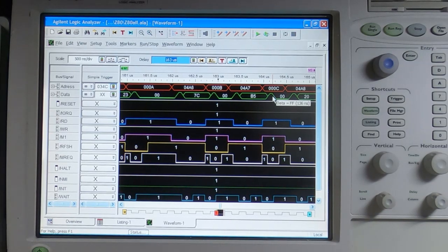So that's not surprising. The value we got from the DRAM when we were trying to do the memory check was 0000 as well. So it looks like that value is always returned from RAM, and that includes when the processor is trying to pop the return address off the stack, and in this case that's obviously going to cause it to reset. So it looks like the issue at the moment is that the value being returned by the RAM is always 0, irrespective of what's been written there, and then obviously that is going to cause a few issues.